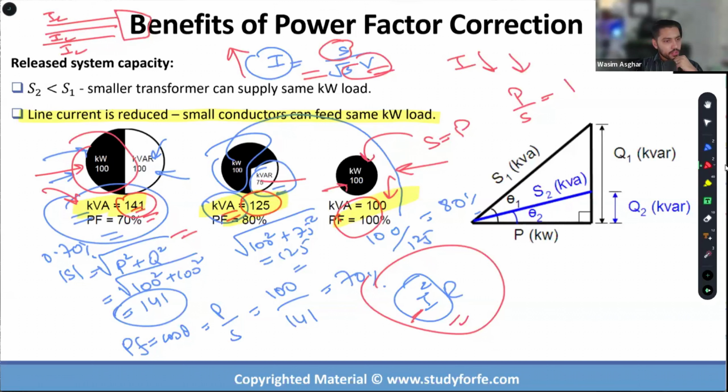So there's a question. Is it fair to say that these two things about the high motor load customer: power factor varies on loading of the motor, low power factor with low loading, and it's time dependent? Number two, we can also use active power factor correction. So the assumption is that you're looking at a facility holistically, right? You're looking at one industrial plant, and the makeup of the load is going to change. Some motors are going to be online, some offline, some motors are going to present a little bit different power factor, different loading conditions, and whatnot. But we are looking at the big picture view.